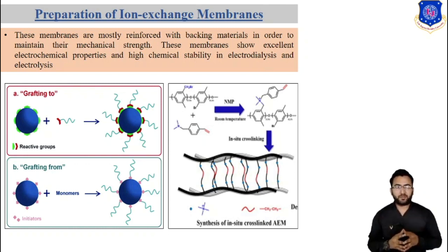Other kinds of ion exchange membranes are obtained by subsequent sulfonation of a film, of which the conventional film is prepared by the copolymerization of styrene and divinyl benzene, and by casting a mixed solution of polystyrene sulfonic acid and another inert polymer, the latter case being suitable for the preparation of charge reverse osmosis membranes. In order to increase the concentration of exchange groups of the membrane, sometimes hydrophobic groups are also introduced into the membrane matrix. This method gives low diffusivity of salt and low osmosis of water to the membrane.